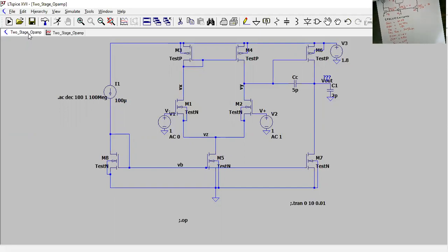After that, you can modify slowly and check the effect of each transistor on the desired simulation results. After you meet all the specifications and make sure you got what you want, you can also run transient analysis, showing for a small sine wave how your output is going to be magnified.